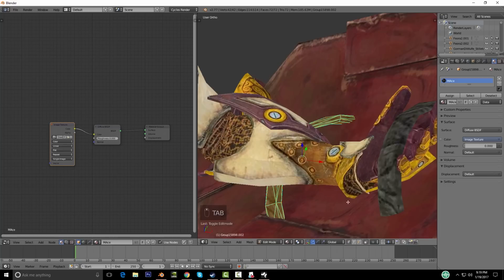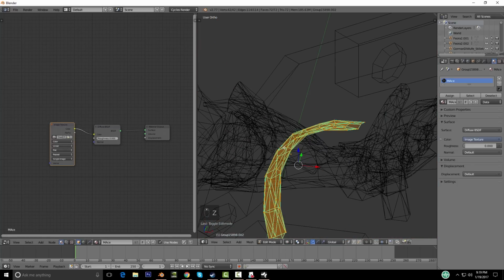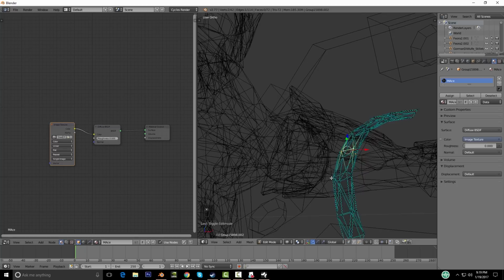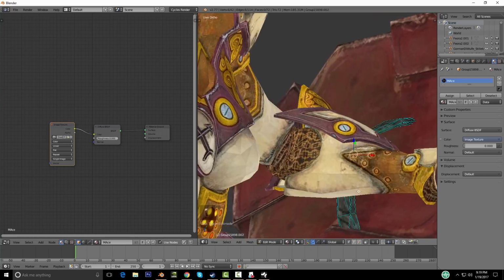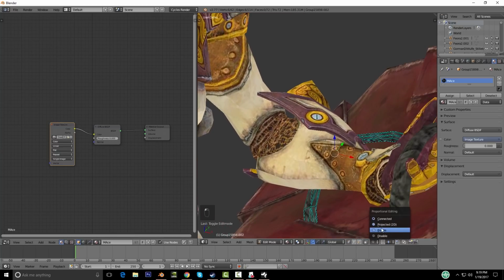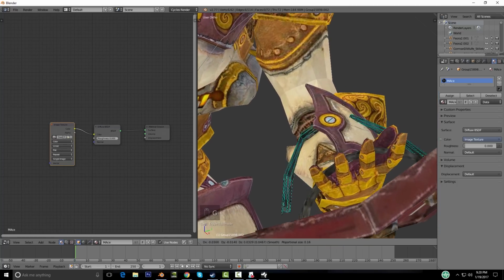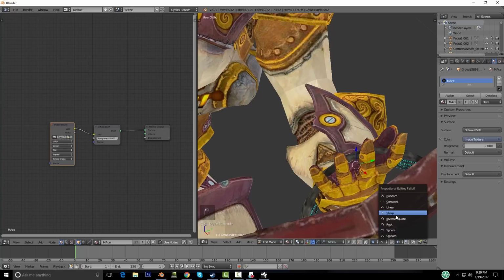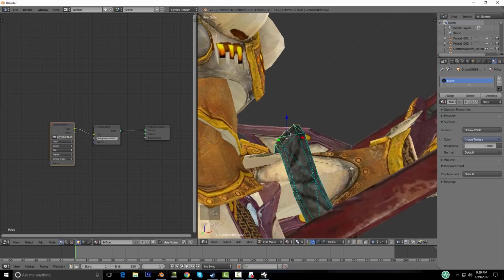It's a little hard to see at the moment, but we're just going to hit Z. I'm going to hit C, and that'll let us actually use a brush to select. So I'm going to select all the vertices in the center there because we just want to control all of those. Going to right click to get out of there. Go back to material view. Going to turn on some proportional editing again. Kind of get the angle where we want it and grab it. Let's see. This might be a bit much.